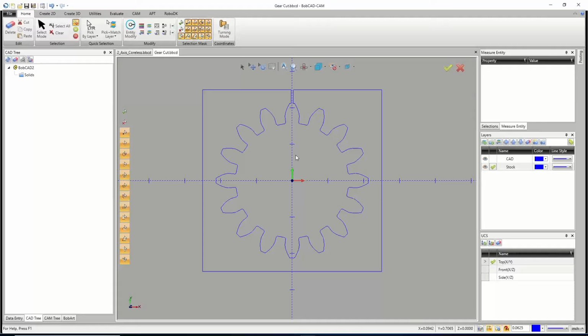And a lot of times with wire EDM, if I have a solid model, one of the steps I take is actually extracting the edges off of it to get just the wireframe, because I can't use surfaces for wire EDM, so there's really no point. I'm really just using edges, and if it's a 2-axis, I could do an edge with a taper. If it's 4-axis, I need the top and the bottom edges of the part, and I'll pull up a quick example of that and go through a little 4-axis near the end here.